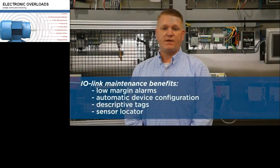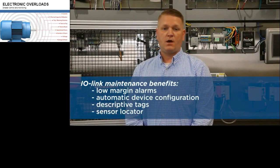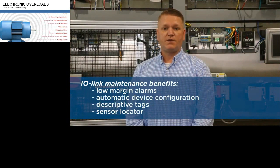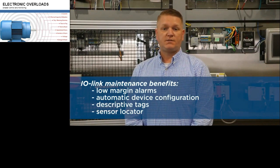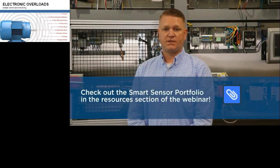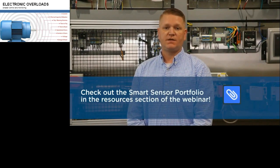IO-Link gives you some maintenance benefits that include low margin alarms, and automatic device configuration that allows for sensor parameters to be pushed out to the sensor instead of having to teach them on the line. You can create descriptive tags for each sensor, even turn on a sensor locator to help locate the exact sensor you are looking for, plus much more. In the resources section of this, we have created a smart sensor portfolio that goes into more detail of all the smart sensors that Allen Bradley has.